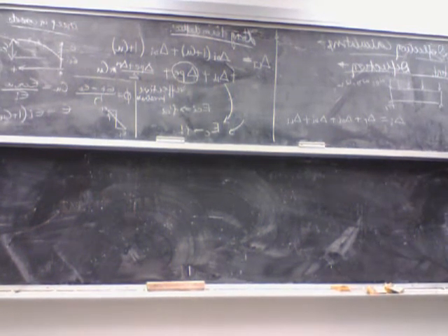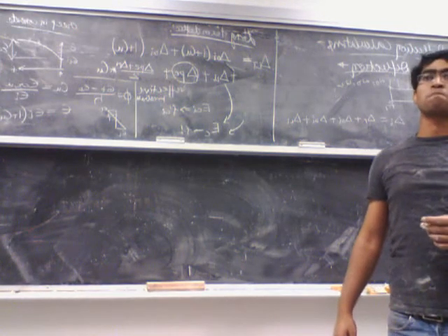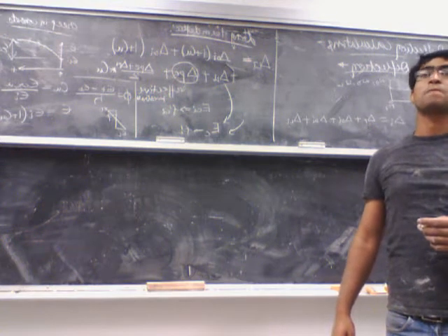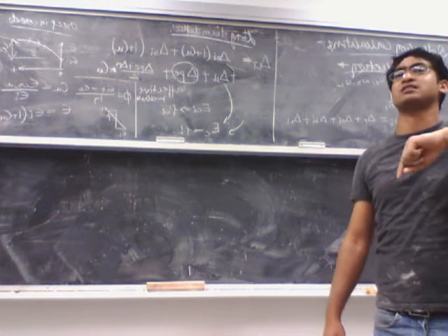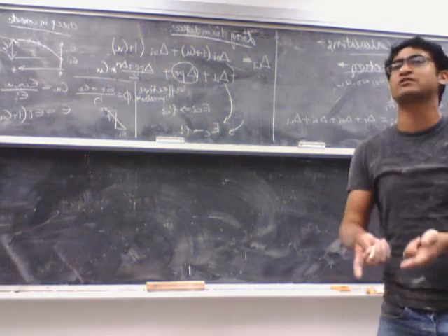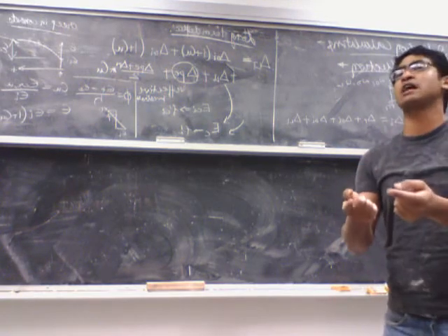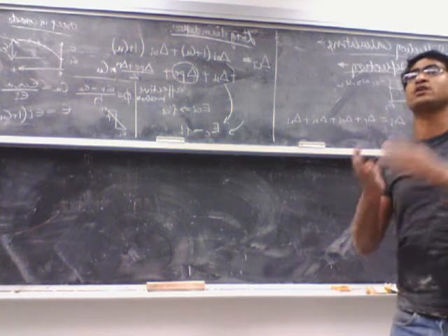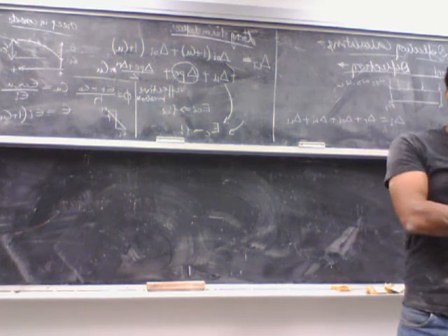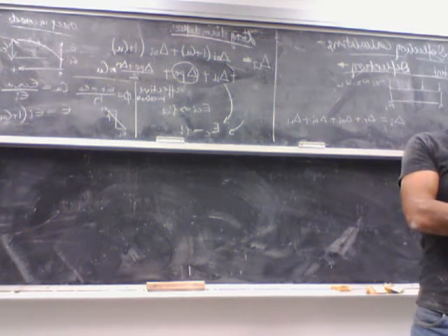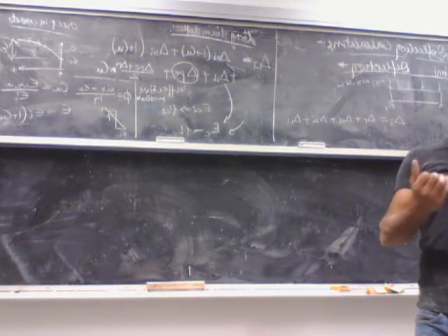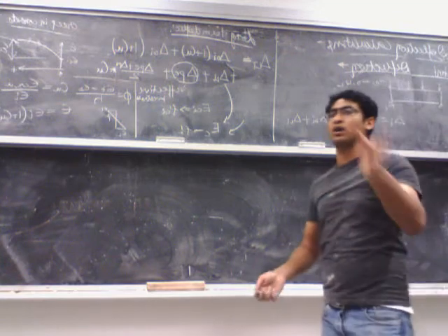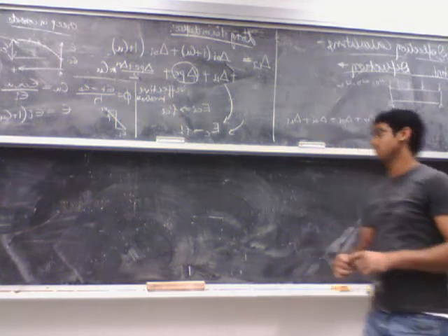So if we're doing instantaneous deflection without the creep being included, but we're still including whatever. Instantaneous doesn't mean it's right after stress transfer. Instantaneous means as soon as the load is applied. So that load can be applied right after stress transfer, or I could apply that load at service condition. Okay, so then the usage of ECI or EC never changes. No, it never changes whether it's a long-term or an instantaneous deflection.